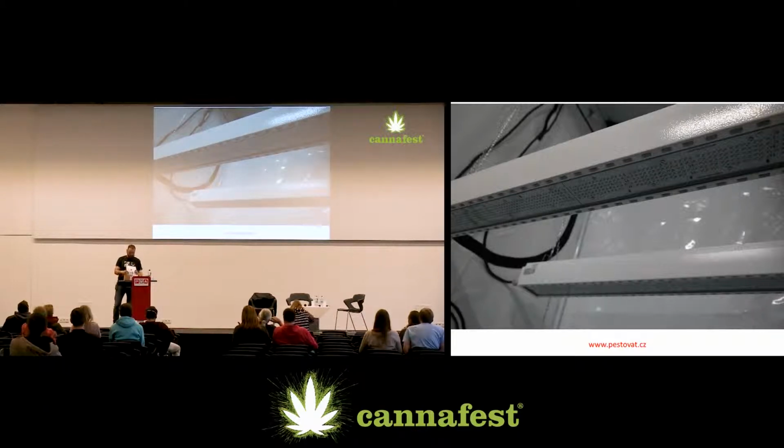That's what I've learned, that if you use LED modules, it is important that the chip does not overheat. So you've got to cool it. If it's warmer than 60 degrees C or something like that, then the activity of the LED module is much lower. It won't any longer produce as much light as promised by the manufacturer. And as expected, there are 2 types of cooling. One is active cooling using air, where on the LED modules you have fans that would cool the control board, the chip.